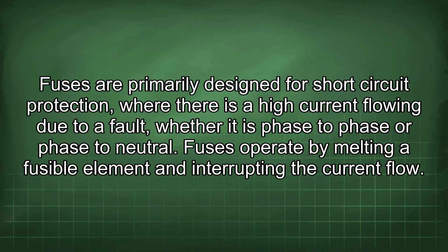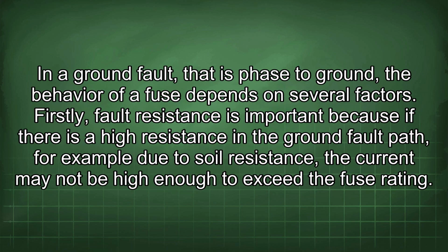Fuses are primarily designed for short-circuit protection, where there is a high current flowing due to a fault, whether it is phase-to-phase or phase-to-neutral. Fuses operate by melting a fusible element and interrupting the current flow. In a ground fault that is phase-to-ground, the behavior of a fuse depends on several factors.